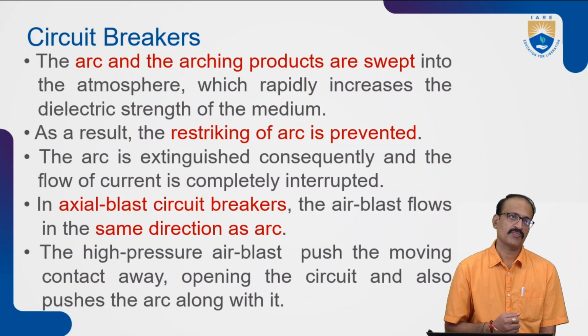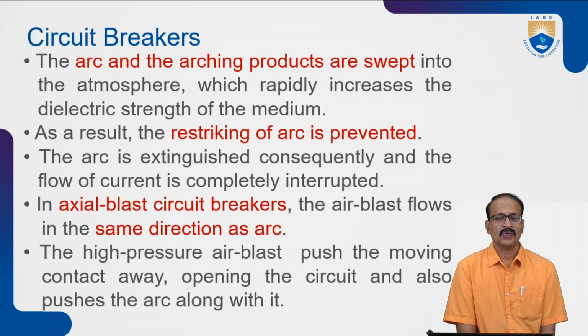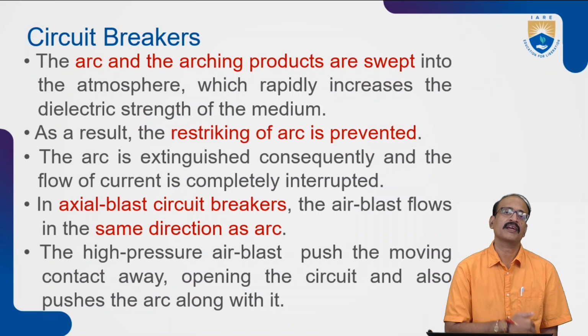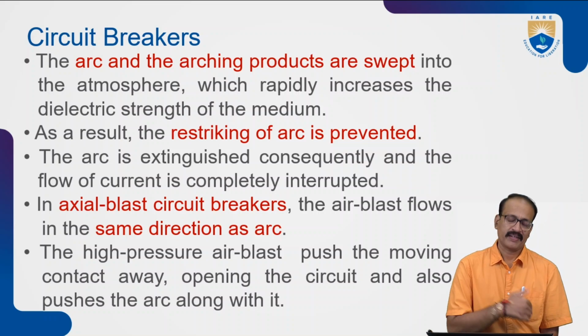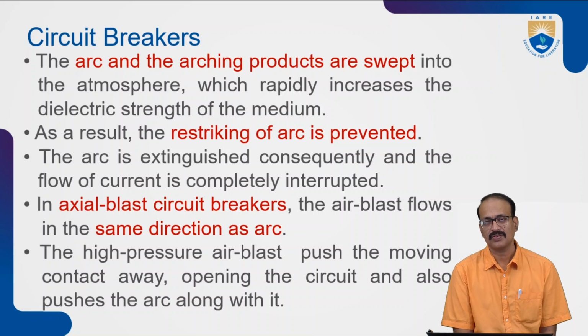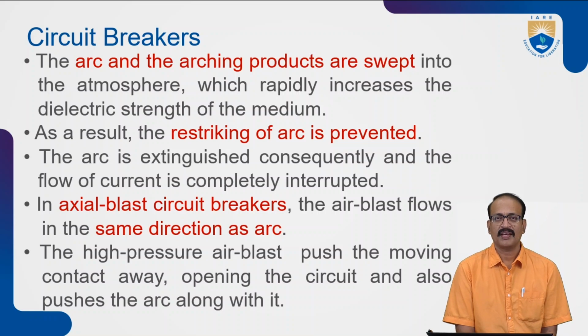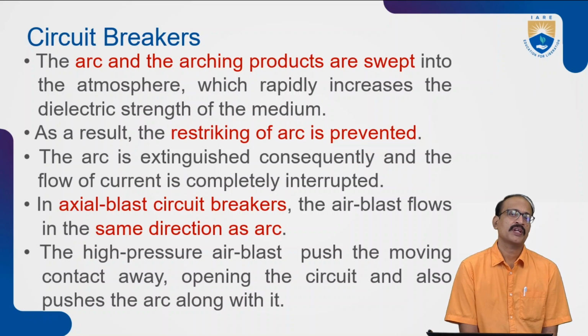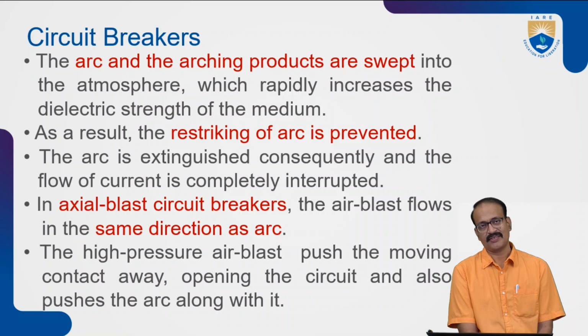Once we sweep these particles into the atmosphere, the normal dielectric strength which should have been there will come back again. So now there is a high dielectric strength between these two contacts, and there is not sufficient potential to break this dielectric strength.